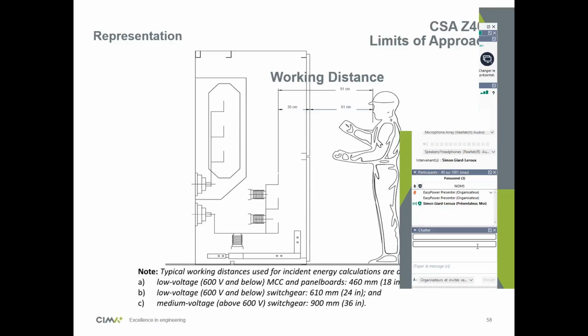So I have another question. Is installing a genset on standby with lower kVA than the normal service running only critical loads? I'm trying to figure out what this question means. What I'm getting at is that if you run your genset at standby versus normal service, the arc flash will be different in both cases because the power rating will be different. So in your arc flash study, you should do a case with the standby rating, and you should also do a case with the normal rating. Then you'll have two different energies, and you pick the worst case one for the label.